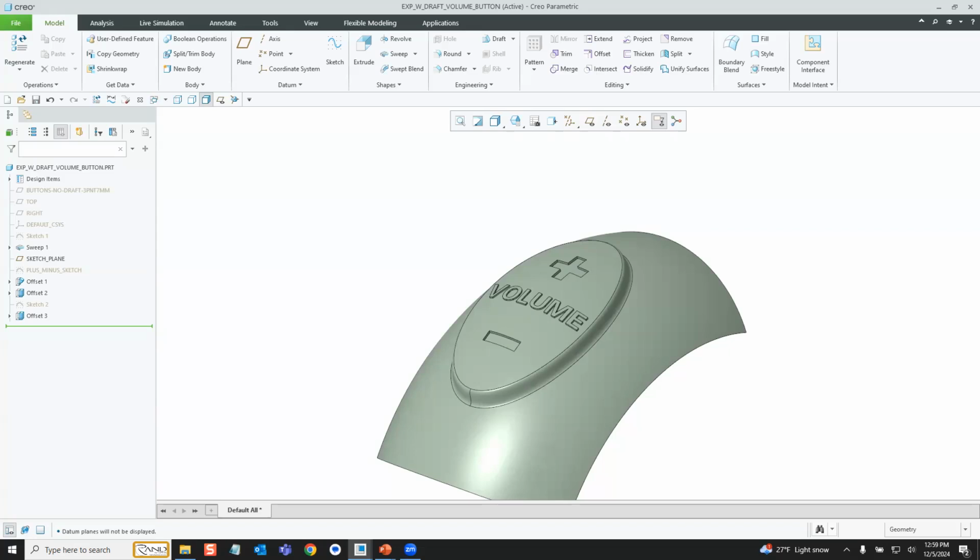Not necessarily. So when you do the automatic fit and the controlled fit, it's going to vary the wall thickness where it had to. The true wall thickness was impossible. That's why we did the automatic fit or the controlled fit. So you do have a variable wall thickness there. Okay. Thank you. Yeah. And that one where I got the bottom to eventually sit flat, it wound up making certain areas way thicker than the number I typed in to do that. I got it. Thanks. The only one that gives you the perfect constant wall thickness is the normal to surface.